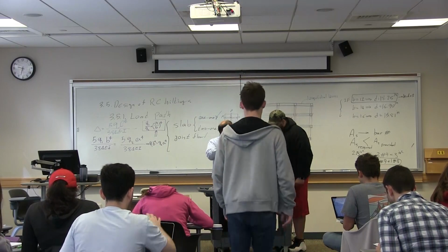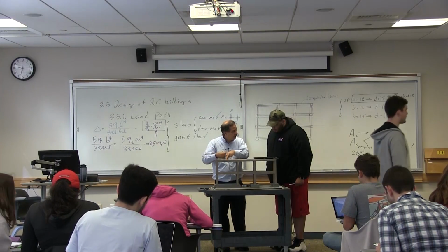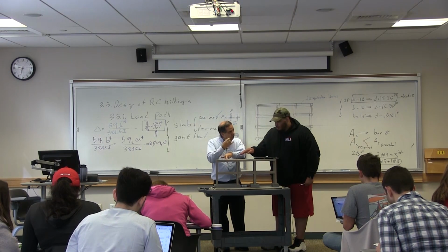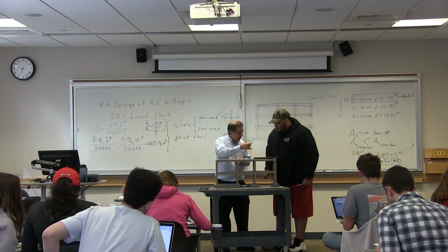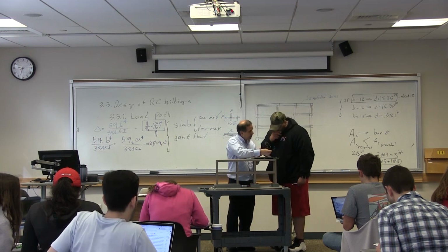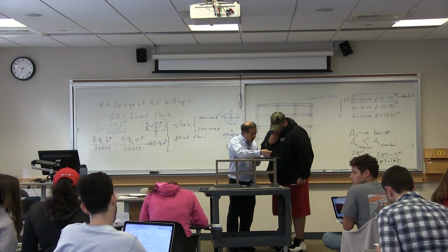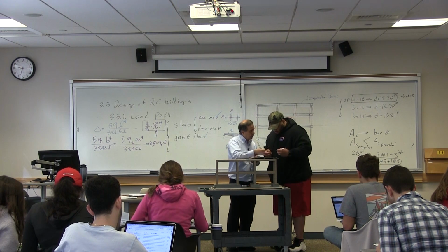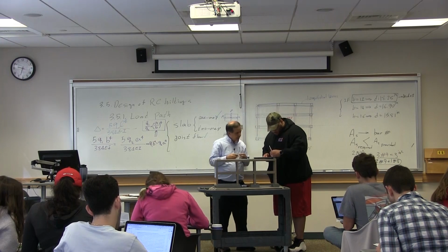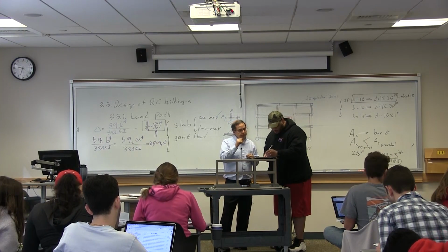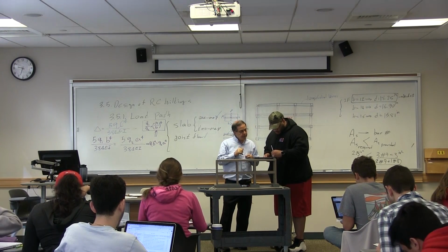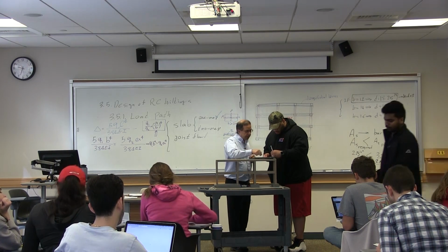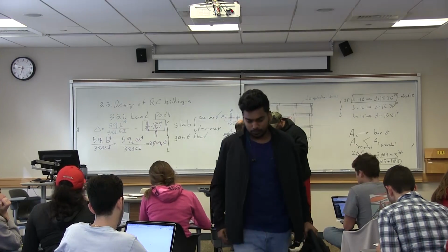How much of your weight goes to this beam? How much of your weight goes to this beam? Most of your weight goes this way. This tells you how much distributed load in the longer direction, how much distributed load in the shorter direction. So this beam is longer. This is B, this is A. This was larger than 2A, not A.